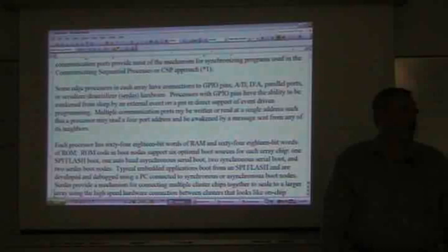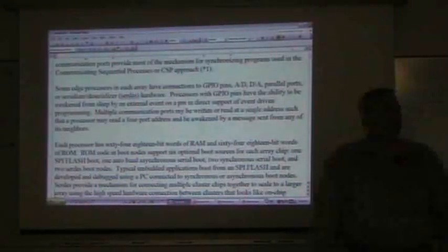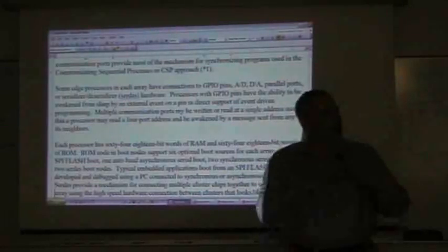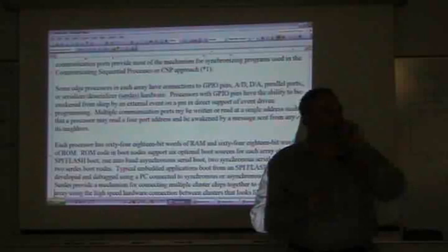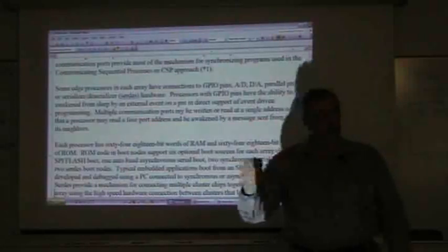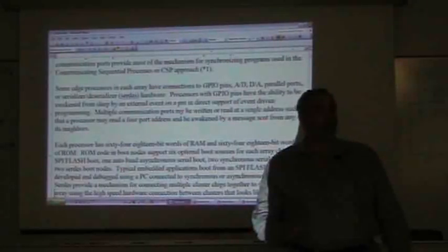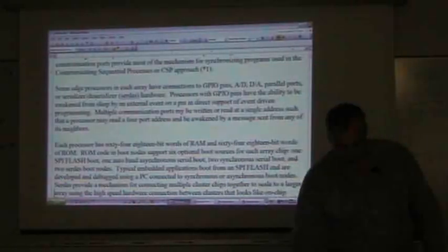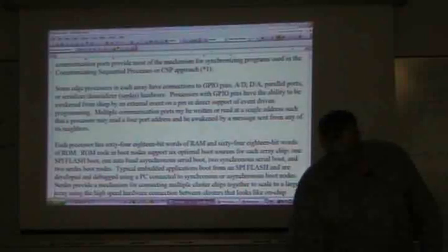One of them is that if you do have a lockup, you know right where to look. You've probably made some change to the data flow somewhere that's no longer balanced. But more importantly, while you're designing your program, you can actually first design it around its data flow, write your diagrams for how the data flow is going to work, and then generate code templates from that data flow. And I'd like to show you an example of doing that.